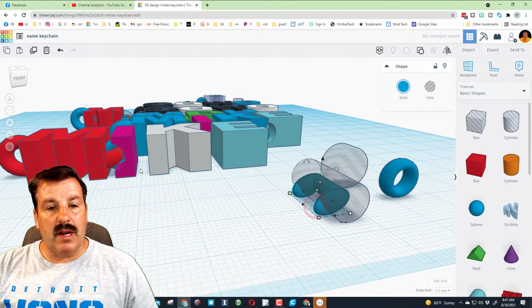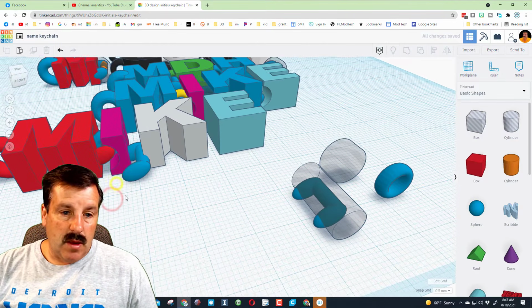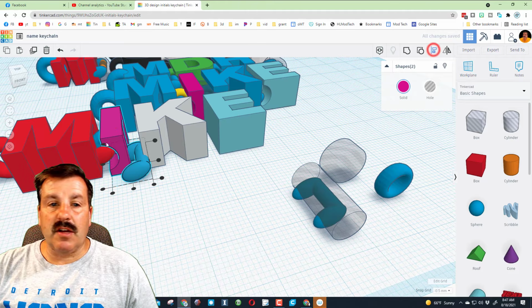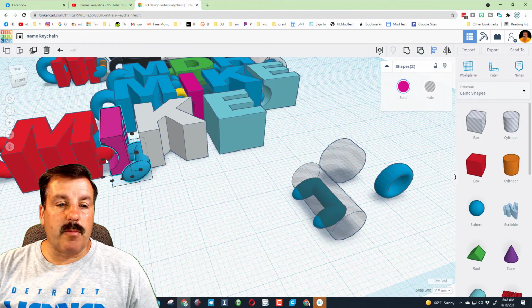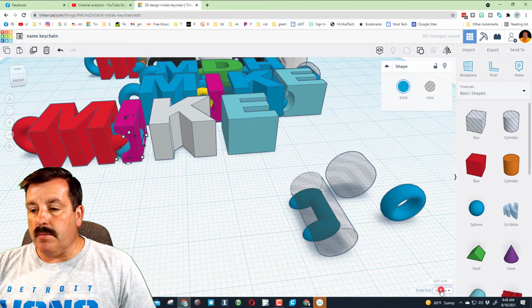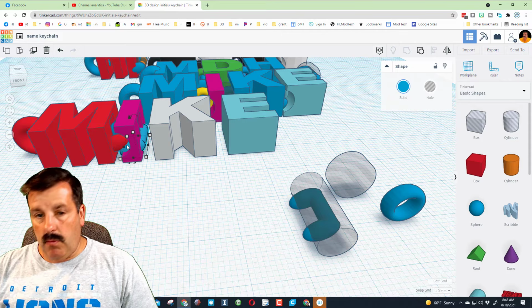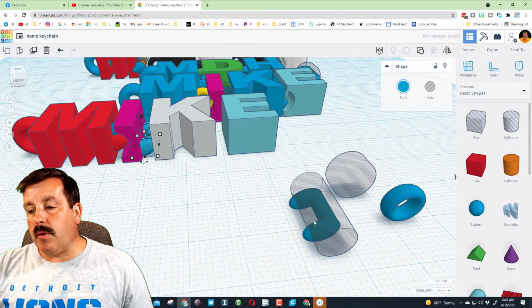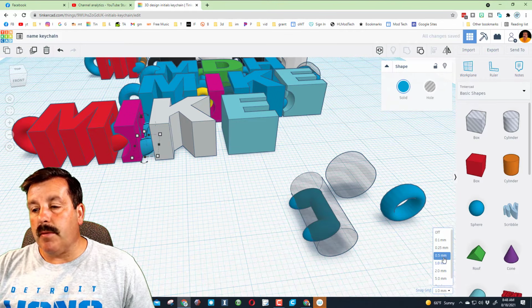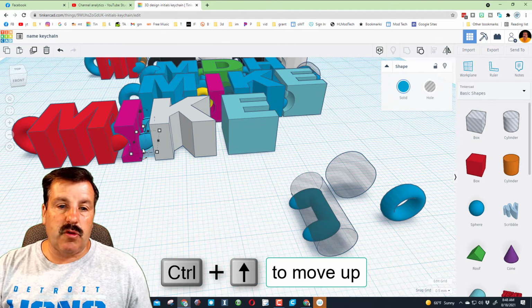And we need to make one of these on this side. Remember, we do Control D. I'm going to select the two, click Align, always make your letter your master, and we want to go center, and we want to go front edge. Remember, we wanted to nudge it 4 millimeters forward, so real quickly, let's switch back to 1 millimeter, and we want to go 1, 2, 3, 4, and then we want to go 1.5 millimeters up, so that was switch to 0.5 millimeter and go 1, 2, 3.